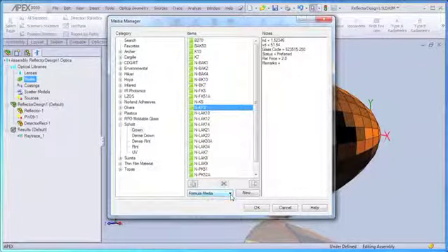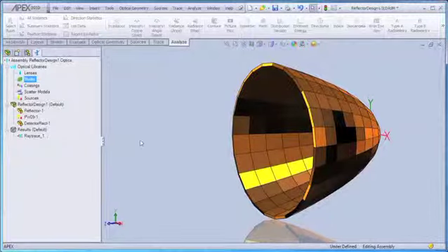And we'll note in passing that we can create a new material using either a formula like a Sellmeier formula or an isotropic material using tabulated data. And these materials can be included in an existing catalog or in a custom catalog, which we can then choose for a new part. Now, we don't need a media type for a reflector, but we might like to assign a coating to our reflector.